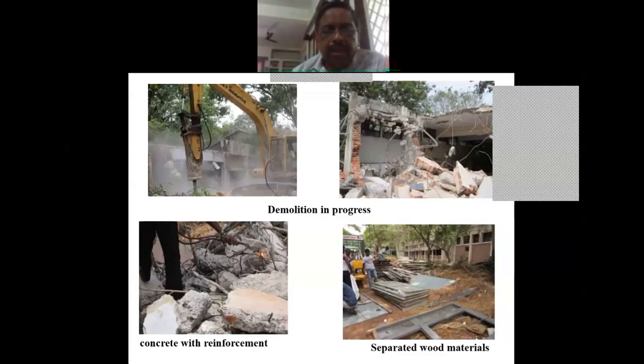But what this government rule says is that if you are producing more than 20 tons per day and/or 300 tons per month at a demolition site, then you have to segregate it, you have to clear it, and you can try to use it in the construction itself at the site. So those are the stringent policies the government has taken.